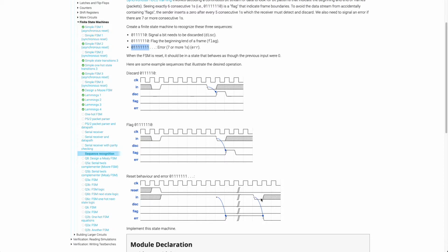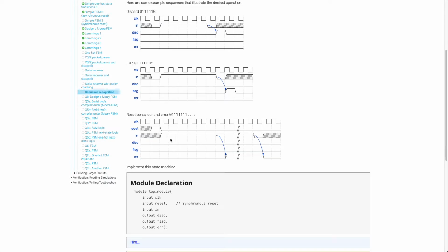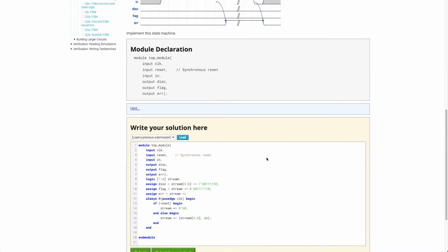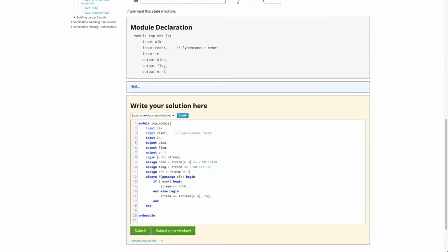As soon as, so this will be all ones in your byte stream, and then this will be 0, meaning it'll be 1 1 1 1 1 1 1 0, and if it's 1 1 1 0, it actually deasserts it the next cycle. So we're just looking for this, or if this, all ones.